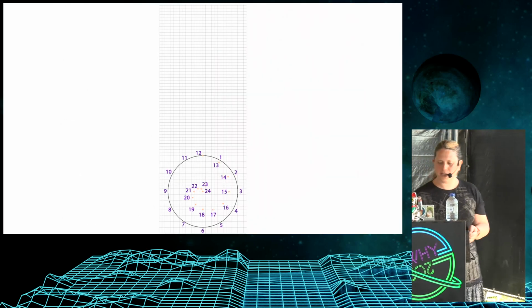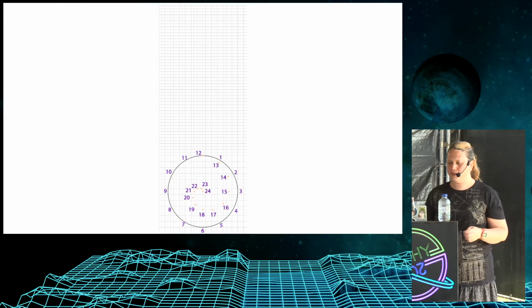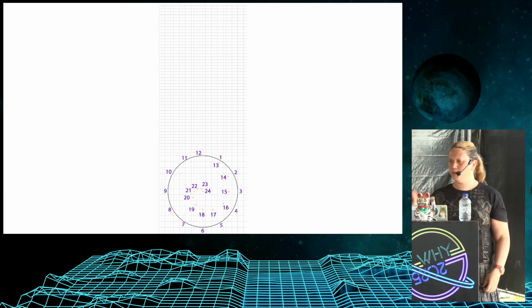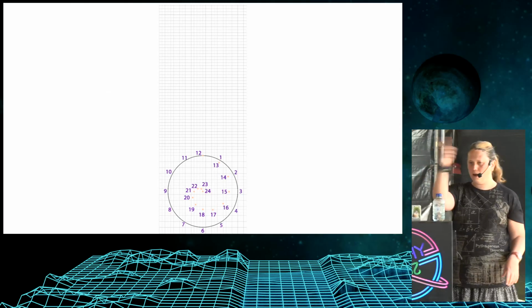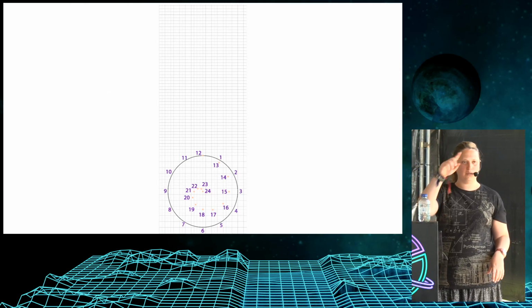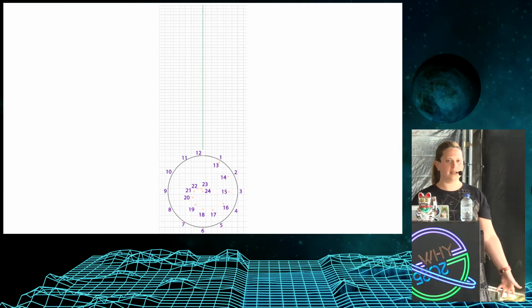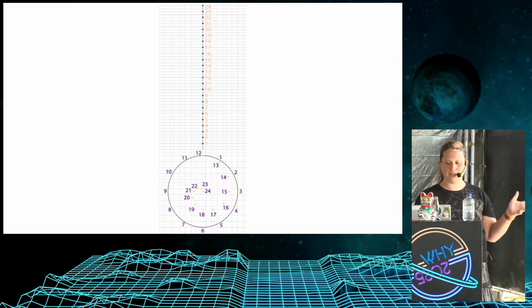So now we're taking our spiral, our auxiliary lines again, and we're adding more numbers. We didn't construct anything new yet. We're still using the same points. We just went numbering them up to 24. So we have the 12 on the circle, and we have the 12 of the spiral. Together 24. Now we'll take a straight line and we'll also divide it to 24 equal sections.